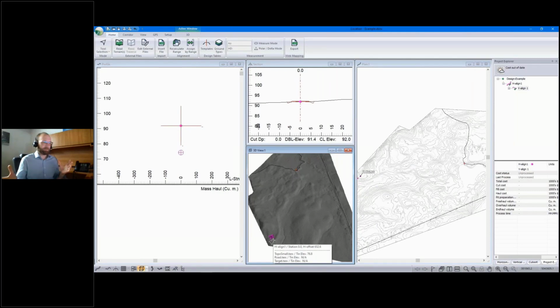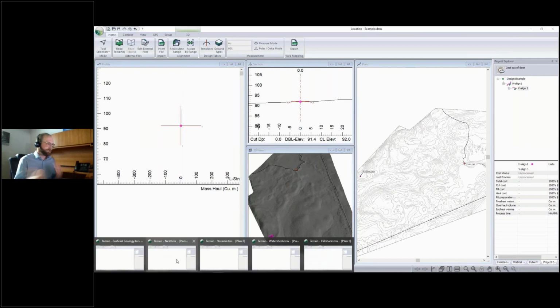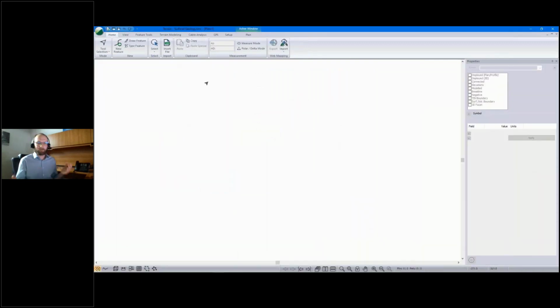So as Jeremy said, we'll consider that. And usually eskers are granular material, which is also usually cheap to build with, and also has less erosion and sediment concerns than if it was a fine grained material. So that's a bonus. But if I'm not comfortable with that, or if I just want to make sure and check other data, well, we can bring in shape files.